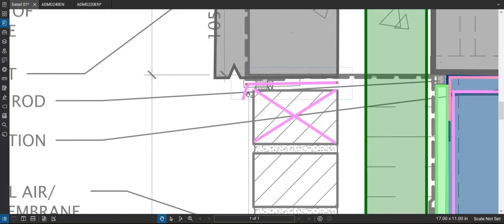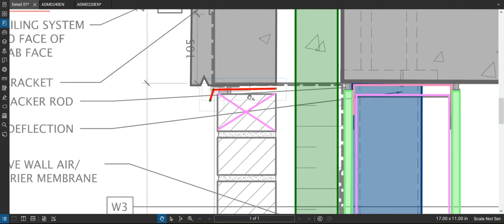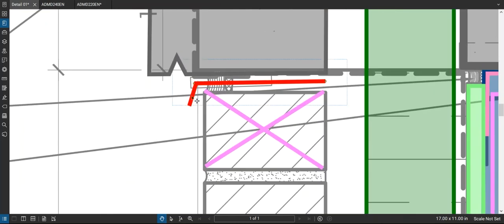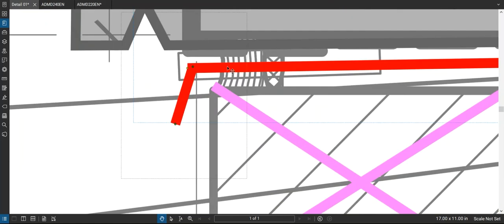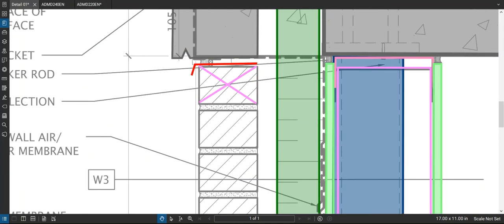So if you start digging into literature, you might see some recommendations of creating that break, basically where the moisture can't migrate from that material to that material from within. So the drip edge is dealing with the runoff on the front, but if the concrete's got moisture within it because it's porous as well as the brick, then it would help alleviate that. And again, you just have to assess that: is it okay to see that flashing edge there? Maybe, maybe not, up to you.